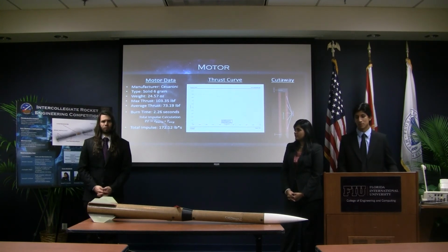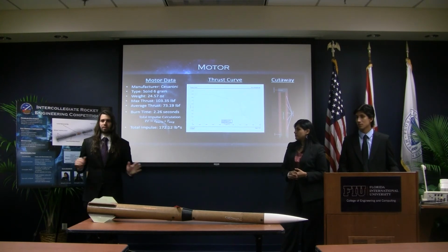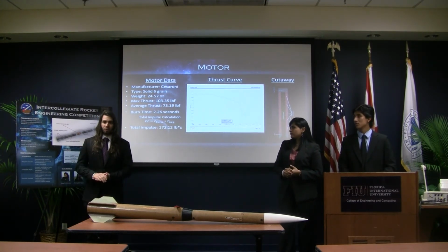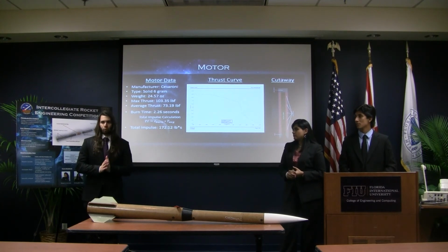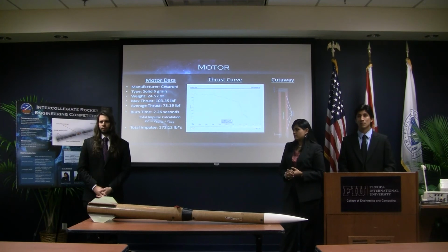I believe 2,000 feet over is going to be about 300 feet per second, which is our max limit. We're overshooting the actual altitude target of 10,000 by enough, so worst case scenario, we're still going to hit 10,000 itself. So it ends up being about 3,000 feet over on best case scenario.